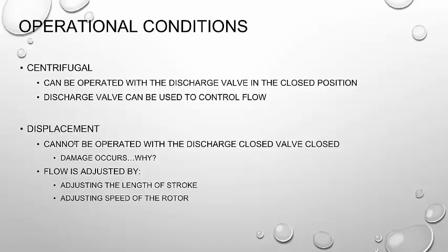The nice thing about a centrifugal pump is I can close down the discharge valve to control the flow. Now, is that efficient? Not really, but I can do it, right? There are other ways to control flow. We have things like variable rate, on-demand type centrifugal pumps.